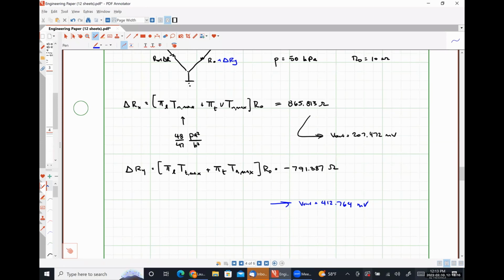We do get. So I'm trying to remember because the overall resistance of this thing from a noise perspective is just going to look like one single resistor having a value of R naught, whereas using single-ended ratiometric sensing, you get half that noise because those two R naughts look like they're in parallel. Yeah, it's in a previous video. Go watch it if you're interested, because I can't remember and my notes are down the hall.